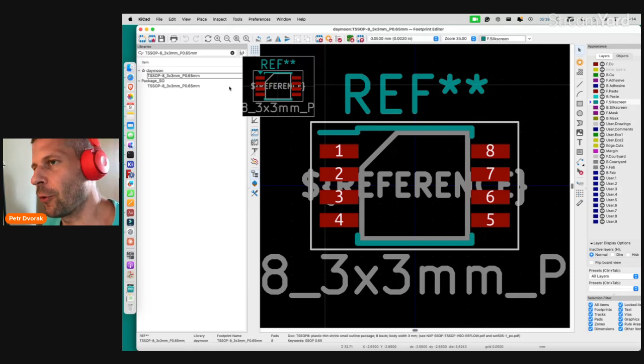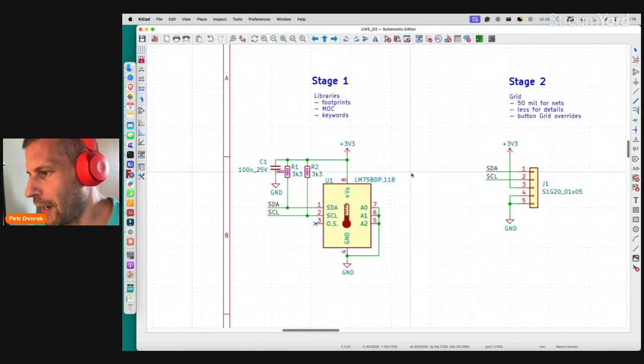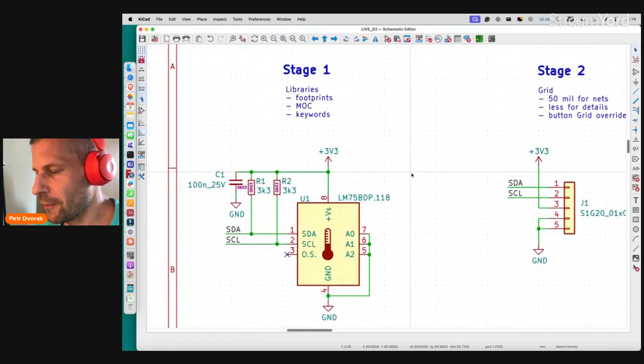But I don't want to give this kind of freedom to KiCAD. I want to use my own verified 3D models. So this is the reason why I choose the STEP file directly to be assigned in the footprint. Yeah, stage 1 I think can be called complete.